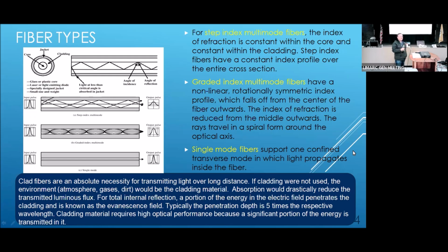Multi-mode fibers have many paths. The last time I actually did a serious calculation of one of those things, a short length of 62.5 micron fiber had 17,000 something discrete paths through the fiber. That would be terrific if we could figure out how to uncouple one path from another and get MIMO in the fiber. But nobody has figured out a practical way to do that. In the single mode fiber, the design spec calls for most standards for 40 kilometers at rates of hundreds of gigabits per second. So that's a really long distance.